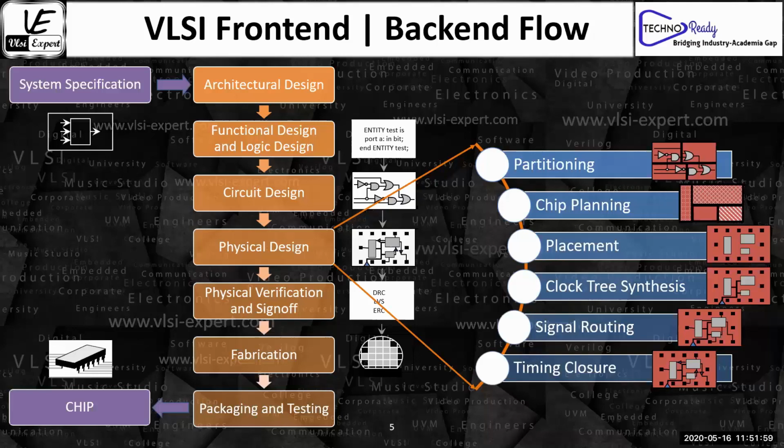Now there is a lot of confusion among people: top level chip planning and top level placement versus block level placement and block level chip planning. Frankly, guys, if you think in that perspective it is always going to confuse you. So just remove that, then it is going to help you. Placement is placement, chip planning is chip planning. There can be one or two rules that differ between the top level, SoC level and block level, but apart from that, everything is as it is.